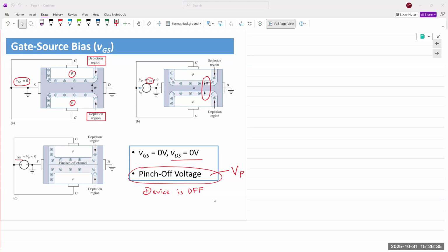Just after everything is done, you flip the device or you flip the connections and just see if it works. And that'll prove whether it's symmetrical or not. If fabrication is symmetrical and everything else remains the same, then yes, the device is symmetrical. You can flip the drain and the source. All right, any other questions?